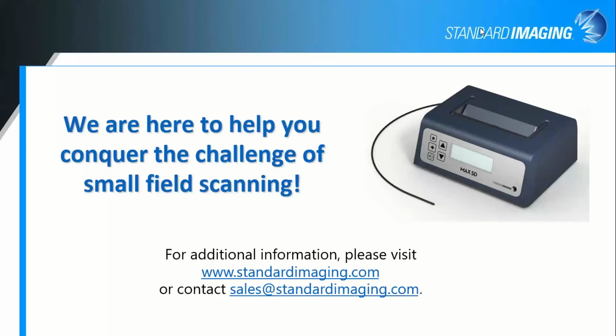And then is there a limited lifespan of the scintillator? Yes, theoretically. I'm not sure I know of anybody who's completely dosed it out yet. We usually recommend that you replace your fiber once the signal goes down below about 80% of the original signal. And really the reason for that is just to protect you from that low SNR causing frustration and causing issues with your measurement, just with the increased uncertainty.